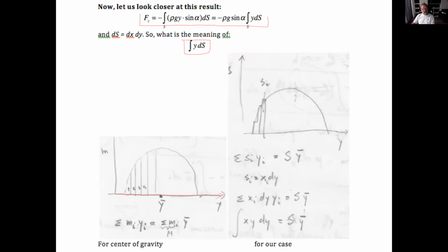So here's a coordinate Y, and then I have different masses on it: 1, 2, 3, 4, each of a mass. And each of them has a Y coordinate. So I claim that the mass is the sum of all the mi. And then in order to find the average distance, which is the center of gravity, I have to take each mass and have its coordinate added up, which is basically doing the moment about the origin.